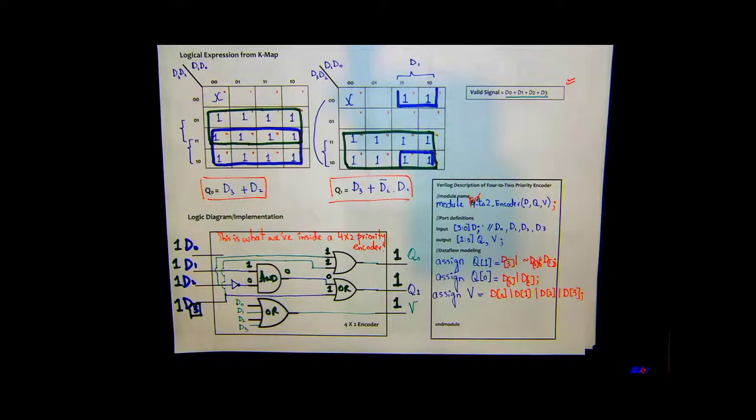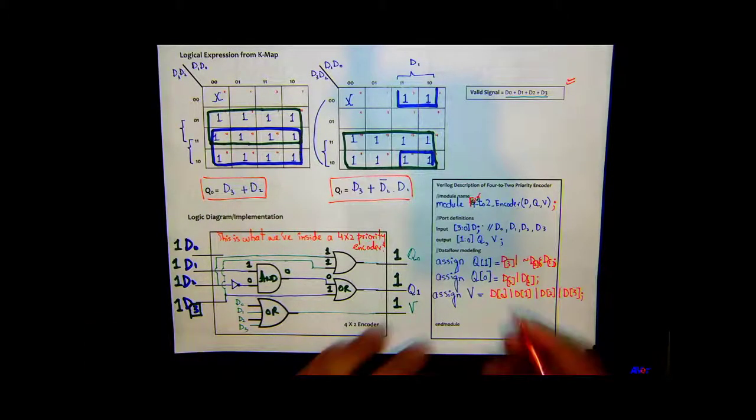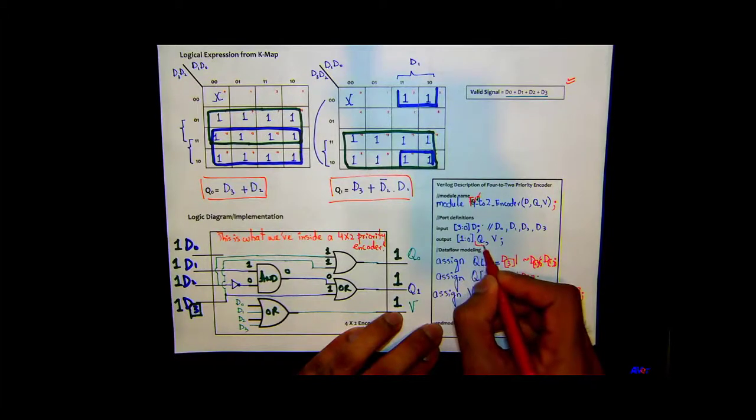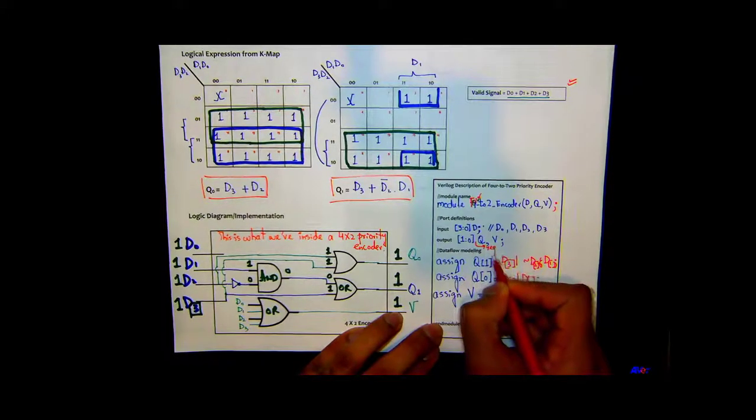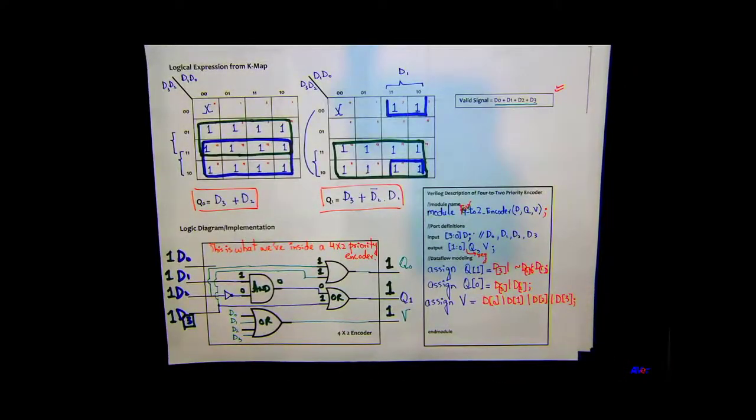Another thing that you could do here, if you like, is put a data type here, which is a register. And I told you guys what a register does, right? A register is going to just store your value there. So once Q0 and Q1 both are 1, they will stay on. Even if I don't add a register, they will still stay 1 here. But with any change to the inputs, they will change. So you want to store them.